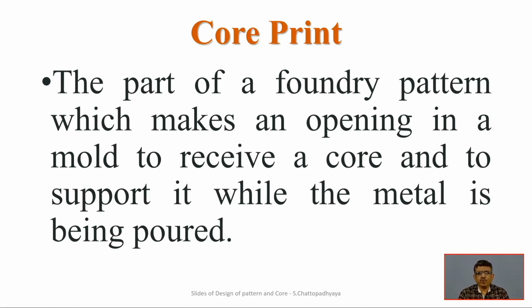The core print is also important. It is the part of a foundry pattern which makes an opening in a mold to receive a core and to support it while the metal is being poured. Somebody has to put a red carpet for the core itself, and the core print is a necessary strategy to accommodate those cores, which are responsible for the creation of the hollow part in a casting.